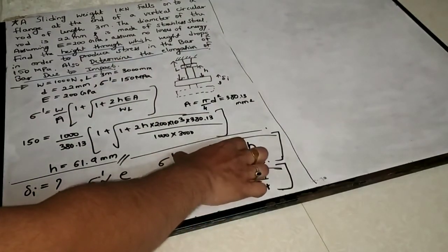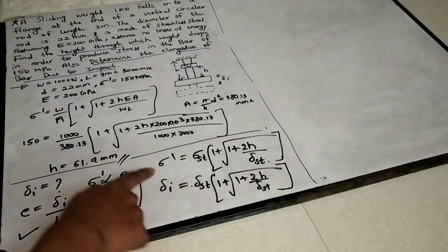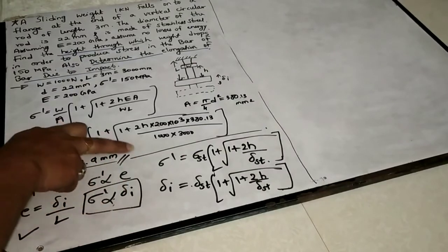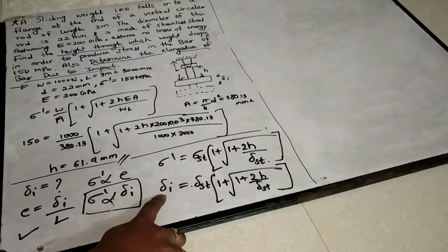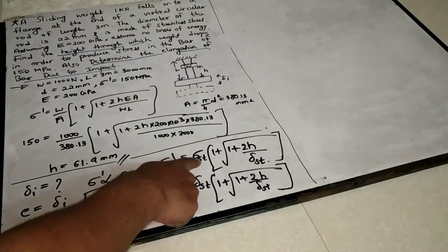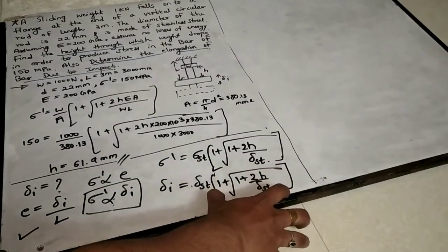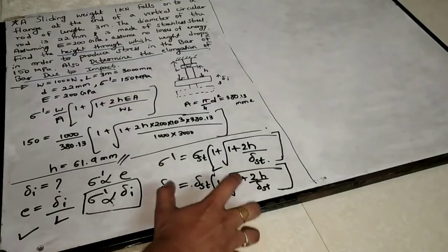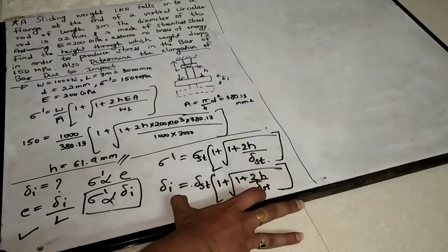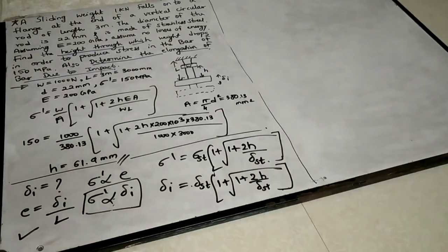This relation we already got by rearranging the terms in terms of deflection. So in place of impact stress or instantaneous stress, you have instantaneous deflection because of this relation. So instead of static stress, you have static deflection, and this will remain as it is. Okay, so you don't find this in the data handbook, but that's how we find this relation to determine the elongation of the bar due to impact. Okay, so you make a note of these things.